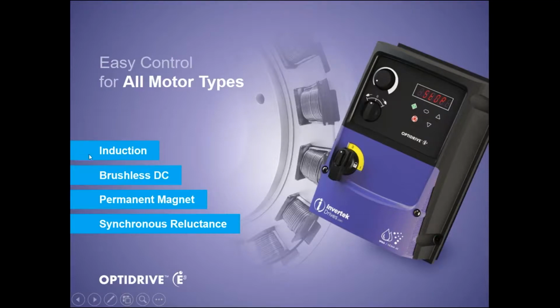The most common are induction motors, but you can also control brushless DC motors, permanent magnet motors, this is open loop without an encoder, and you can also control synchronous reluctance motors. This is for motors with any of the Optidrives from Invertek. This is also for the P2 family, which I will talk to you about a bit later.